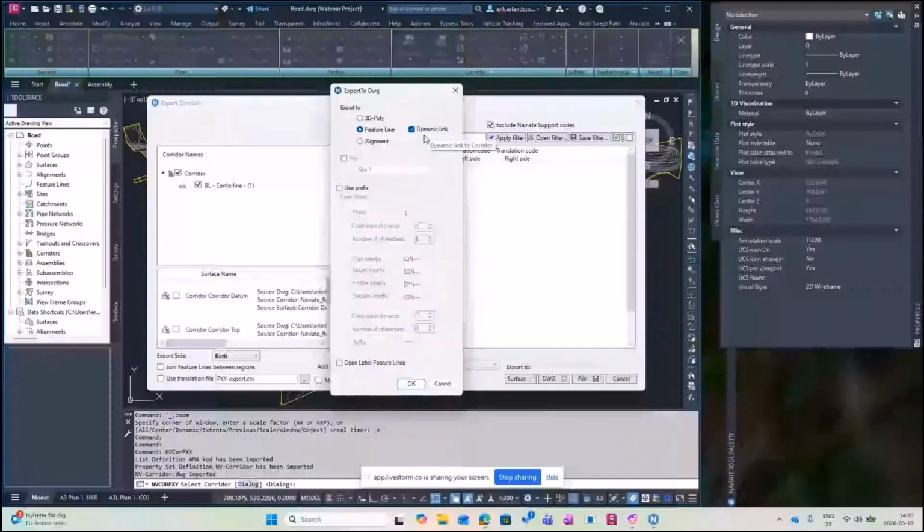As you can see, we have the possibility to add a prefix or suffix to the layers, putting the line objects in the standard you need. For this to work, you have to prepare the codes in the assembly first, which I have not, so I will not do this. Let's click OK.